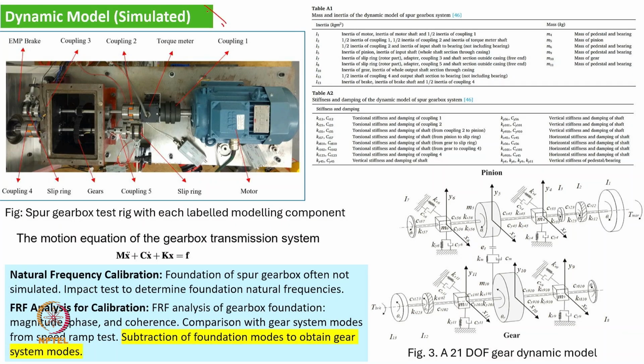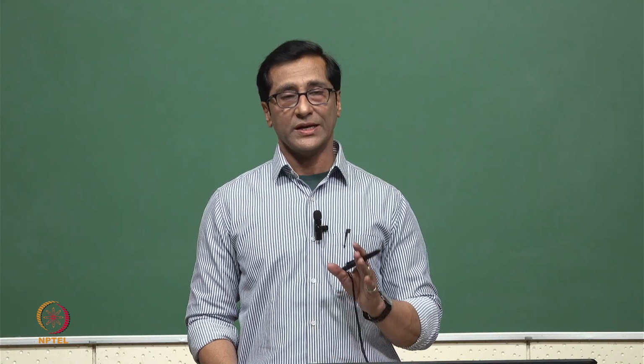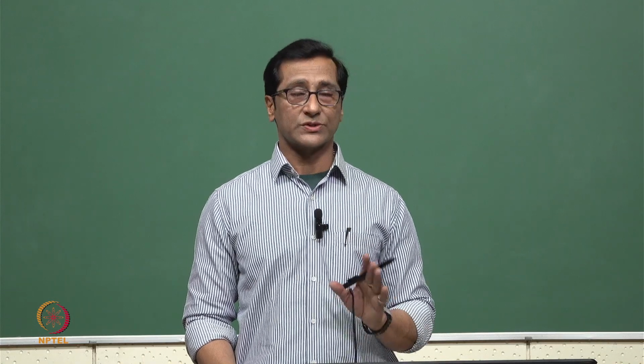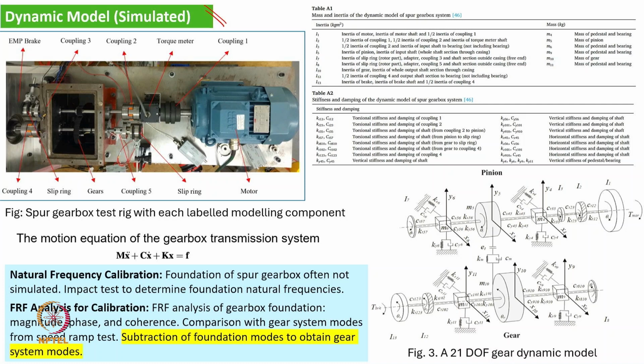So in this case, one more important point comes when we are doing installation. Foundation also plays an important role. We can incorporate everything in the model. That's one possibility. However, what they did was model the foundation appropriately, and they got a signal. Whenever the foundation-related signals are there, then when we are running an actual case, you subtract that. After that, it will be related to the gear pair system only.